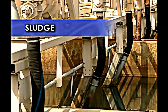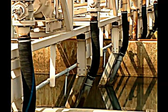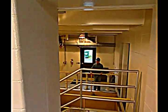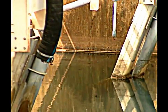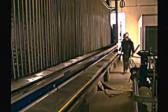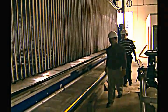Sludge must be periodically removed manually or continually removed by mechanical means. Some plants use hoses to wash sludge down a drain. Others have mechanical scrapers installed to scrape the sludge away. The sludge can be placed in lagoons or on sand beds where it eventually dries out. It can be dried by mechanical dewatering techniques, or it can be sent to a wastewater treatment plant for processing.